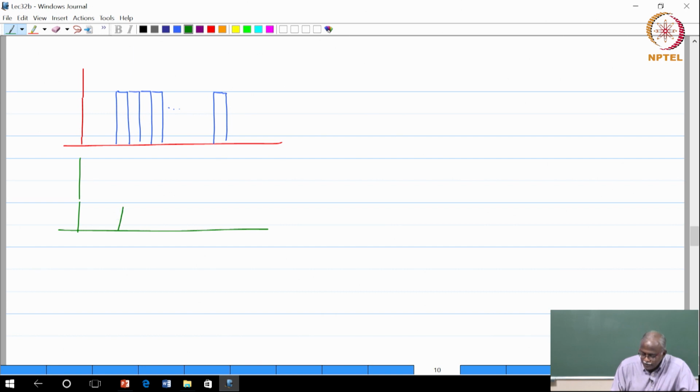In practice, there is going to be some amount of roll off, which means that there will be overlap between sub channels. Okay. So, this is the practical case, this is the ideal case. Now, we know that even if the 2 waveforms are overlapping in frequency, there are certain conditions that you can impose on them to maintain orthogonality. So, therefore, we can generate orthogonality, but this is very important.